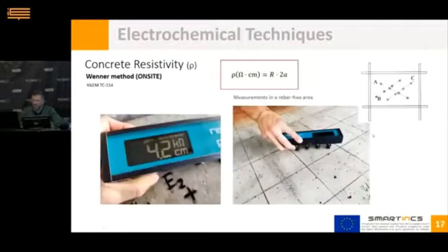In fact, this has led to the method also being extended for use in on-site measurements. The 4-electrode sensor is placed directly on the area to be evaluated, thus avoiding the need for coring, and is therefore considered a non-destructive method.